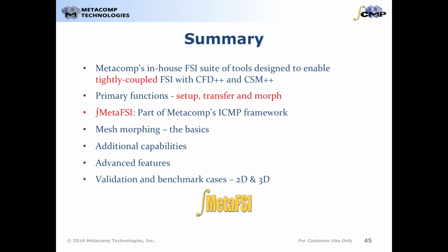We've presented some additional capabilities of MetaFSI, such as the ability to work with MSC Nastran, work with dissimilar CFD and CSM meshes, and integrate with CSM++ to run a transient modal analysis. We've also looked at some of the advanced features supported by MetaFSI, such as displacement relaxation, deformation ramping, and control point augmentation. Finally, we've provided a collection of 2D and 3D validation and benchmark cases using CFD++, CSM++, and MetaFSI to provide a glimpse of the kinds of analysis and the quality of results users can expect when running FSI analysis.